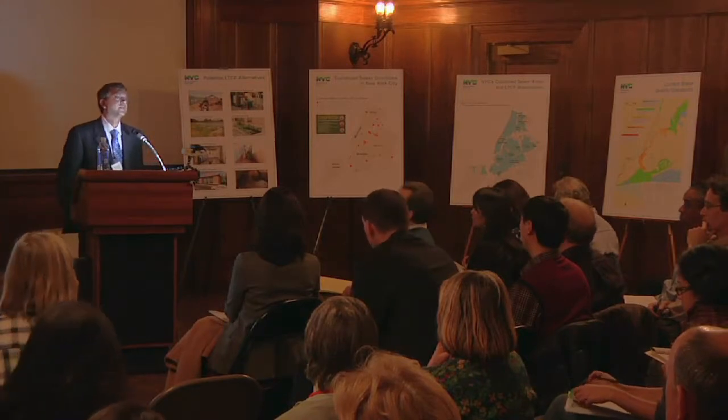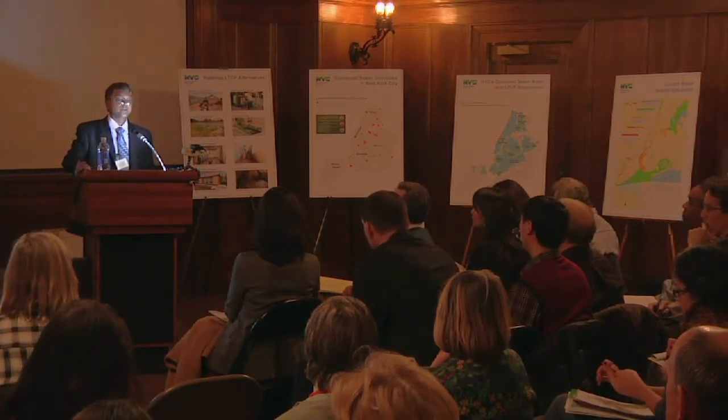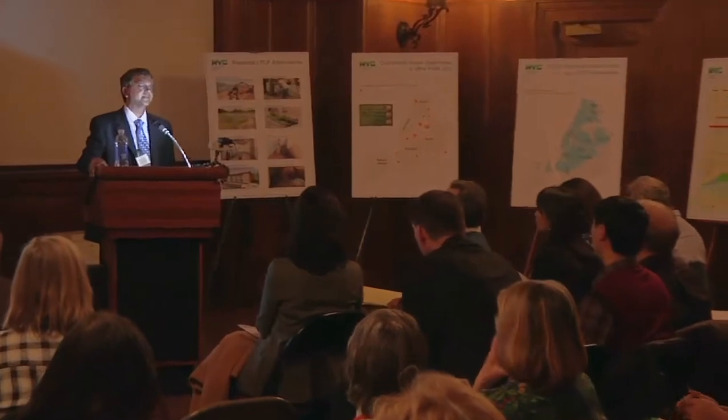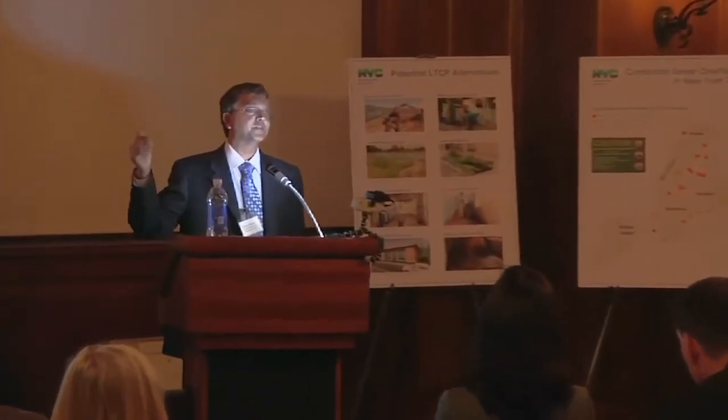Right. But the thing is, though, as the rain volume increases, your fit is going to be a lot better also, because at that point, the pervious area also is acting like impervious area after filling all the. Right. So you should be able to use an allometric correction, so to speak, on your different sub-watersheds and resolve your model just from that data, and that data is already in.